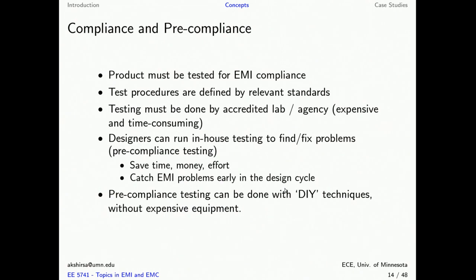Now what is pre-compliance? A product must be tested, as we said, for EMI compliance, and the test procedures are defined by the standards. Before we go to the accredited lab or agency to do the actual test, which can be quite expensive and time consuming, designers typically want to run pre-compliance tests, which are some simple tests intended to find and fix problems before they show up in the accreditation process, in the testing process at the lab.